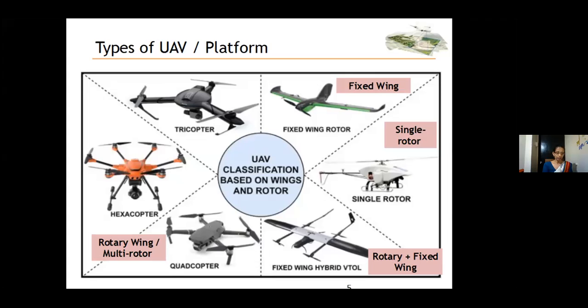Okay, if you need to work with a heavy payload, for example, an aerial LiDAR laser scanner, or have a mixture of holding with long endurance or fast forward flight, then a single rotor helicopter is really your best bet. But the downsides are their complexity, cost, and also their vibrations. So that's why it is not normally used in the survey domain.